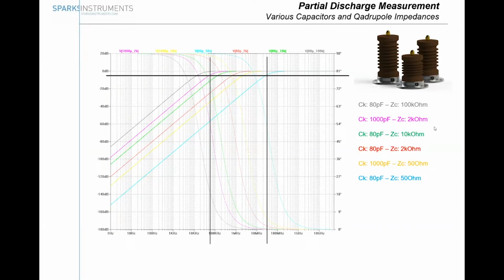So you always have the possibility, whenever you use a sensor which is able to measure in the lower frequency, to cut the lower frequency range with the instrument and dedicated filters to improve the measurement system. But when you use a sensor which already has everything cut, then you might have a problem that you won't see all the PD.